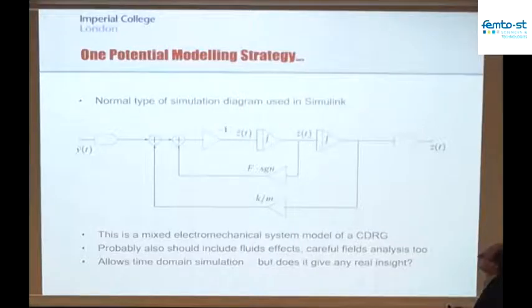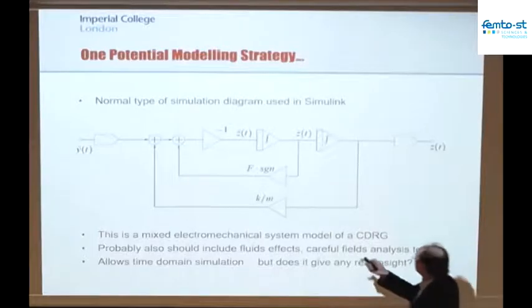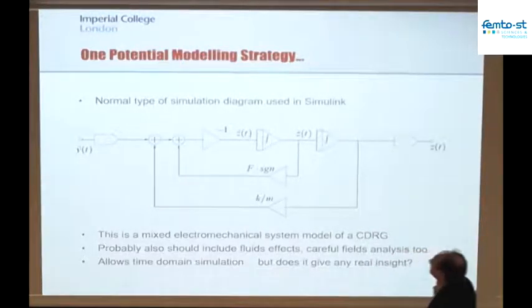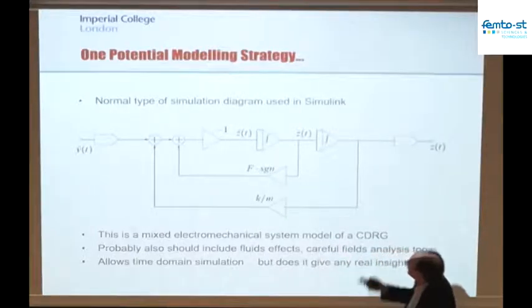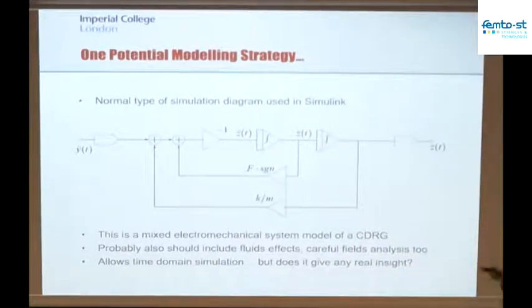One of the things that you can do if you wanted to do a very basic simulation of this type of system is to just put the differential equation into something like a Simulink model. Here you can see a Simulink implementation of the CDRG, where we've got this chain of integrators, as we would typically expect when we implement a second order differential equation in something like Simulink. With some feedback terms here, there's the resonant frequency that's being fed back, and there's also the damping force, which in this case is the force multiplied by the sign of the velocity, which is being taken off at this point.